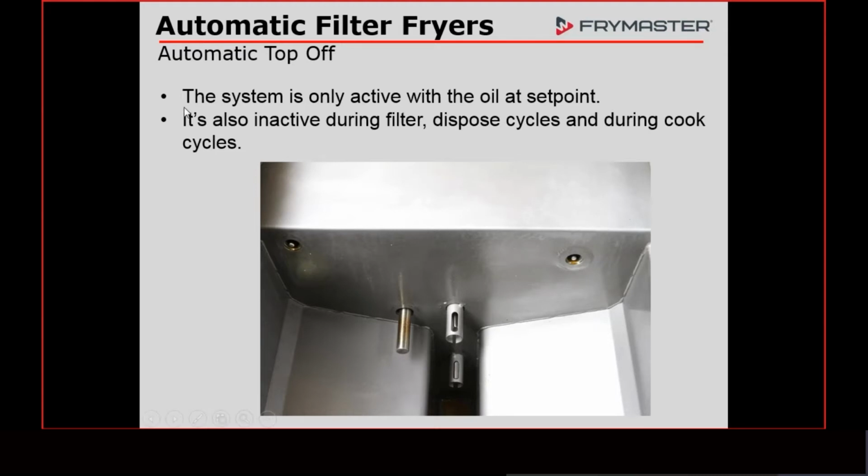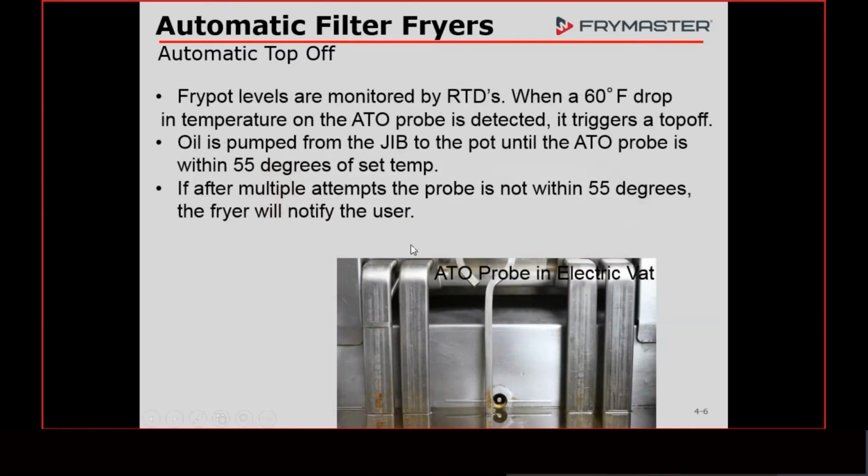So when you turn the fryer on, and once the fryer gets up to set temp, the ATO system engages, and it's going to stay engaged except during filtering, disposal, or during cook cycles. And that's real important because there's some confusion that comes in there, and there are things you can misdiagnose not knowing that. So anyway, that's how the ATO system works.